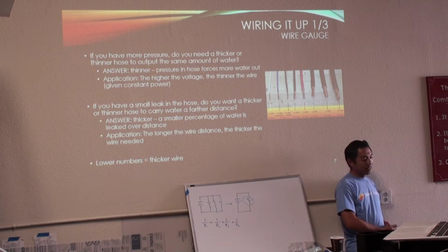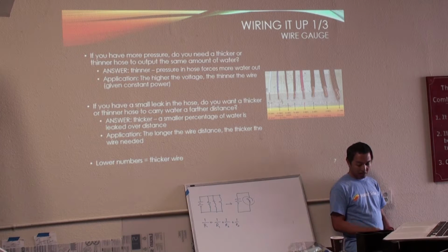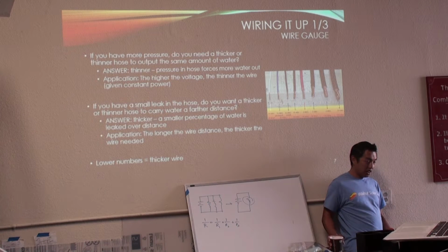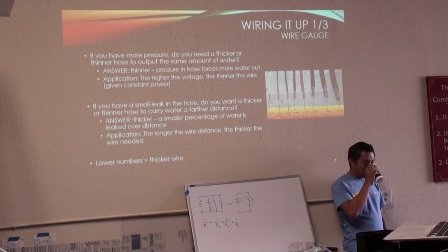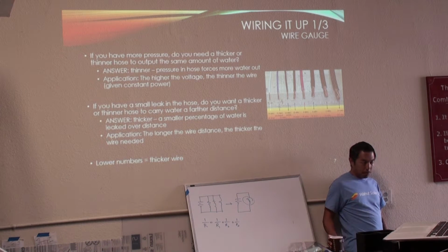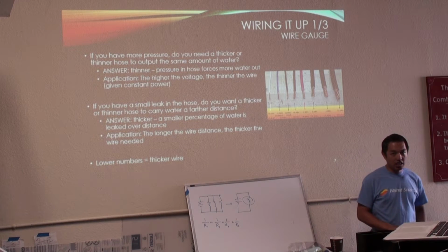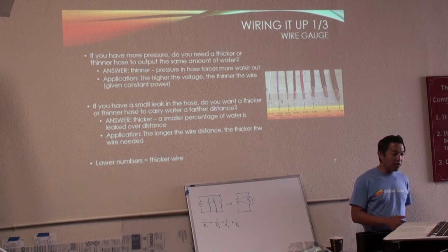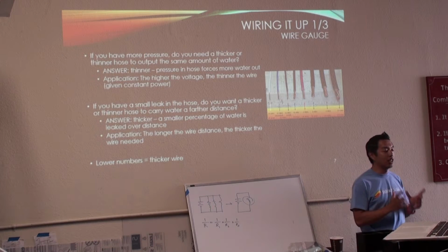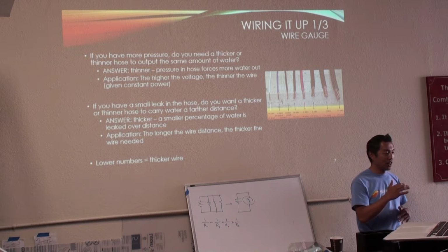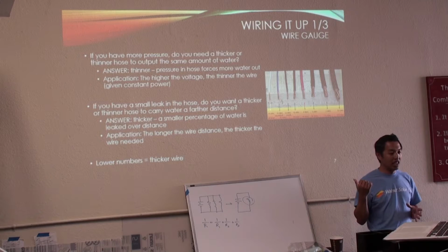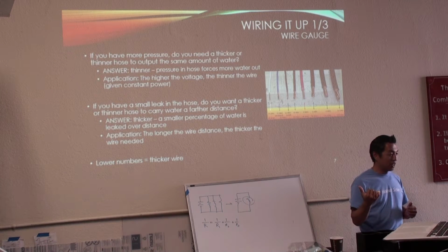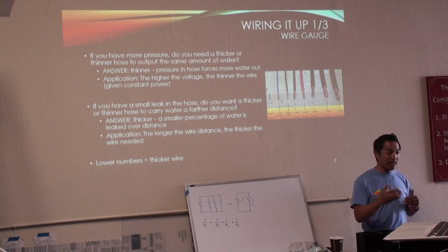You were saying, if we pull too much current, does it lower the capacity of the batteries as well? Yes, it does. If you had a 100% full battery and you discharge that 10 amp hour battery at 10 amps, you will get an hour, that's the rating.